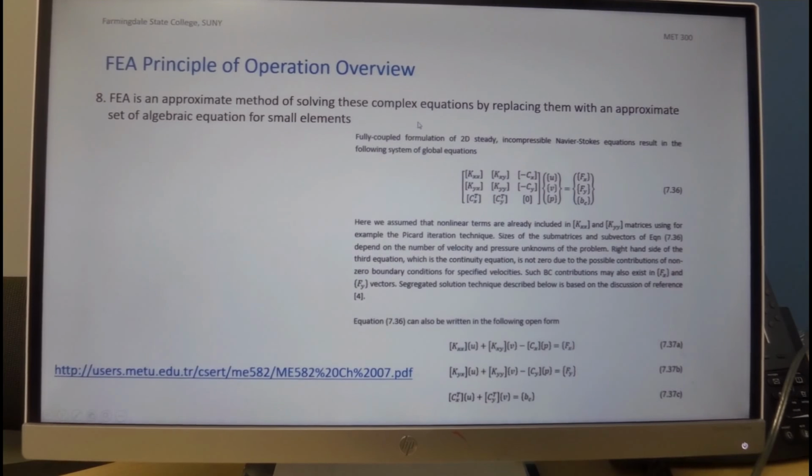The approximated method of the finite element analysis is relating in algebraic set of equations the forces, for example, here in a stress analysis case, to the displacement with stiffness matrices. And these forces are vectors in the various nodes values, and over here these are the displacement at various nodes within the elements.